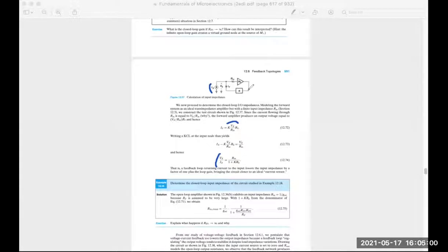What does it mean? Well, the voltage, basically Vx is here. You divide that by Rin. You multiply with RO. You again multiply with K. So this is your current IF. Okay? And putting that into the KCL, this current minus that current gives you this current. So rewriting it, Vx over Ix is this. And as you can see, different than the voltage amplifiers, now your Rin impedance is not boosted up. Your Rin impedance is actually boosted down, right? Well, is it a good thing or bad thing?